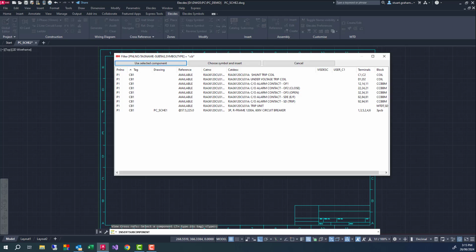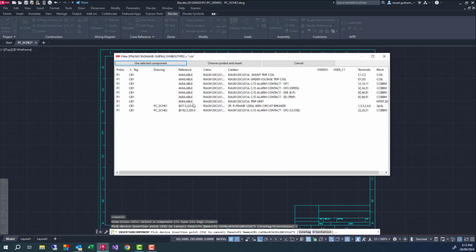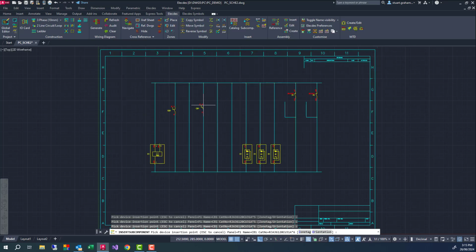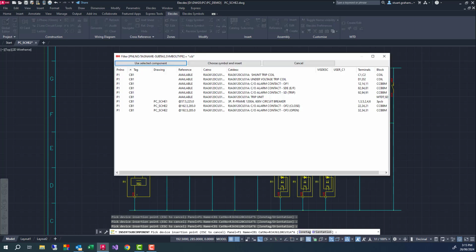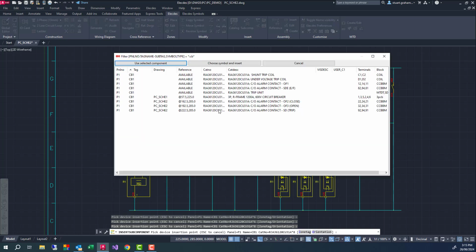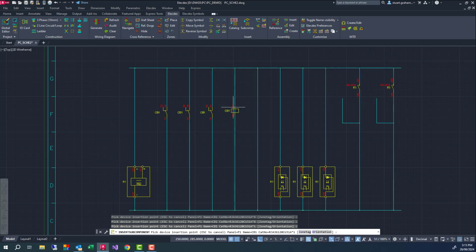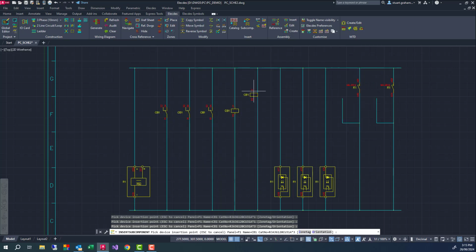These contacts will be used to signal the protection relay, indicating a fault, which should trip anything that depends on the breaker. I'll now insert the trip coils from the CB1 breaker to my ladder. Firstly, the shunt trip coil, and then the undervoltage trip coil.